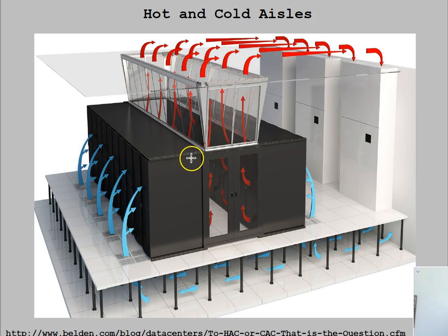We talked a little bit about the hot and cold aisles, and you probably remembered here we cool it from here, and you blow the exhaust up into the little visqueen that I was talking about in the middle, which is that hard plastic, and then you try to just be efficient with recycling that air and putting it through the condenser, getting it to be cold again, and then blowing it back up.